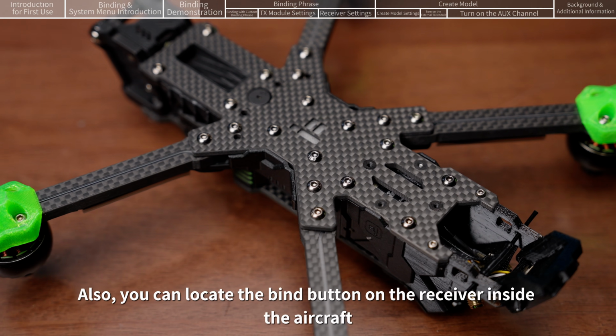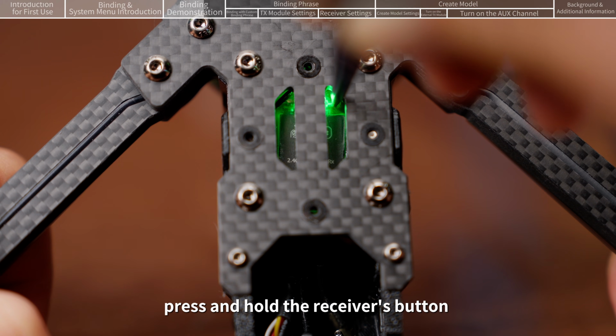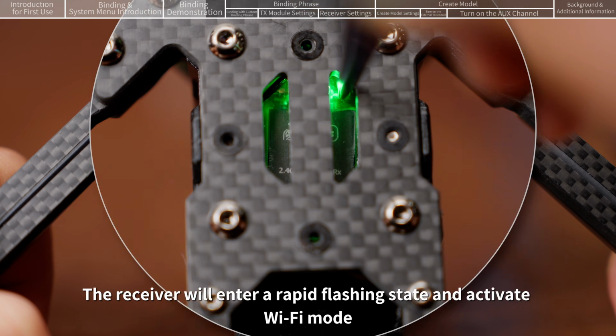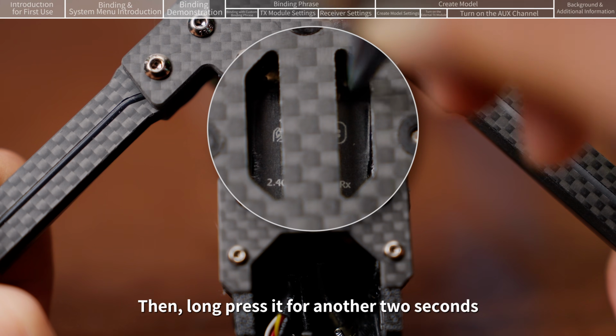Also, you can locate the bind button on the receiver inside the aircraft. Using tweezers or a pointed object, press and hold the receiver's button for 2 seconds. The receiver will enter a rapid flashing state and activate Wi-Fi mode. Then, long press it for another 2 seconds.